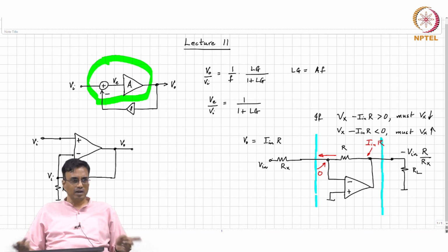So you add V out and V in and compare that result to 0, correct. And how will you add two voltages? KVL of course, but how will you implement addition? Let us say you want V1 and V2, you want V1 plus V2. Can you get V1 plus V2 using only resistors?